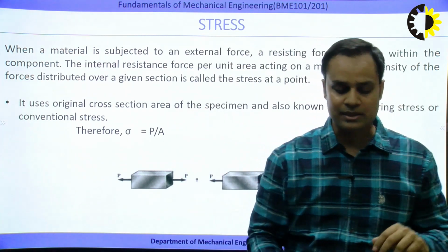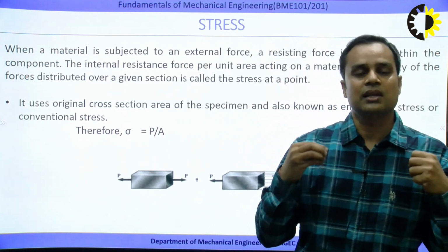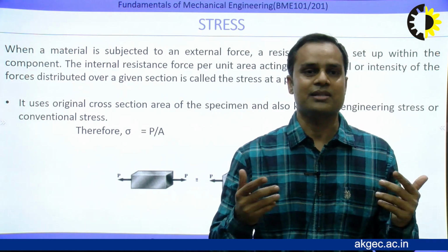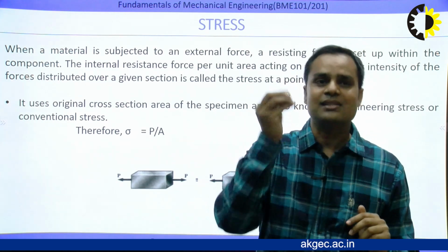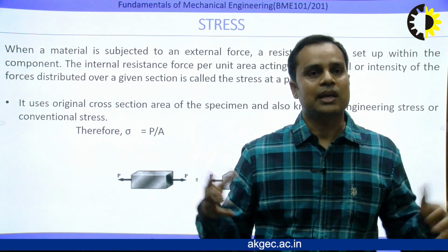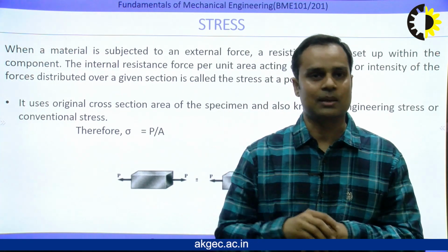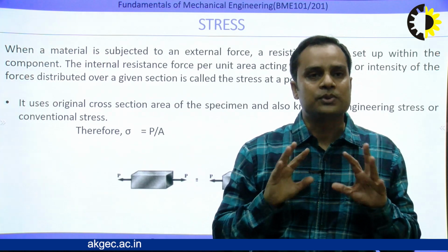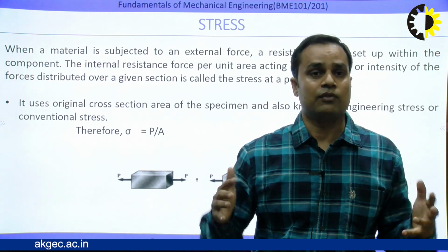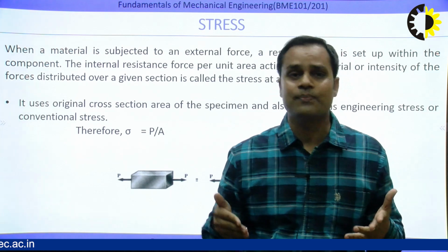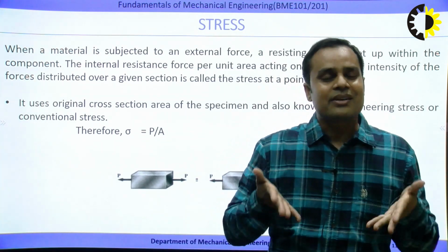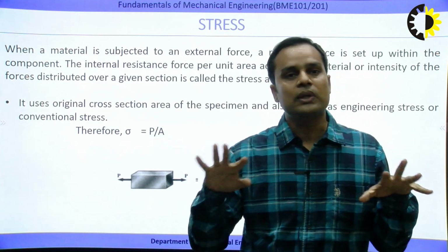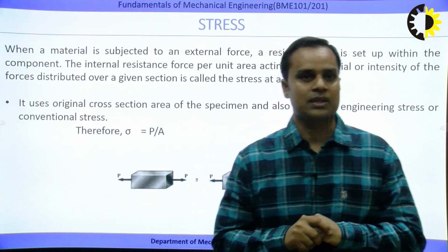So that's why I'm saying that whenever the material is under any kind of load, it has two responses. One is called stress, another one is called strain. Stress can be experienced and strain can be visualized, just like in the example I have shown. After the application of the force on this cup, we are able to observe a severe deformation. This deformation is called the strain. The stress is experienced by the cup, so it can't be visualized or measured. The only thing that can be visualized and measured is the strain.